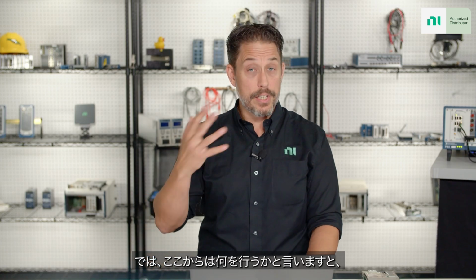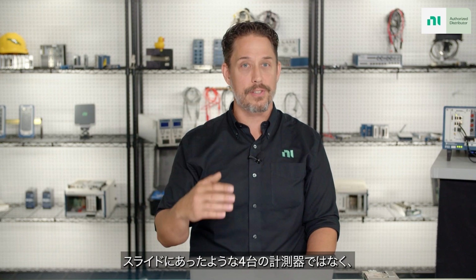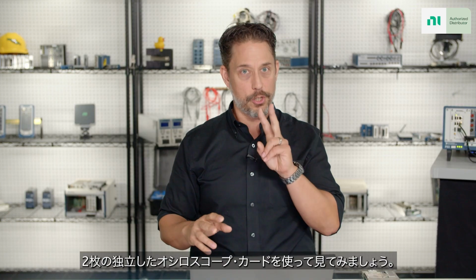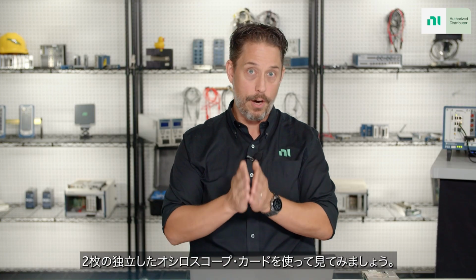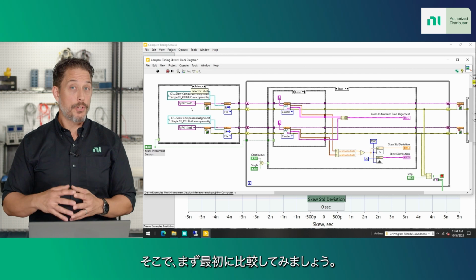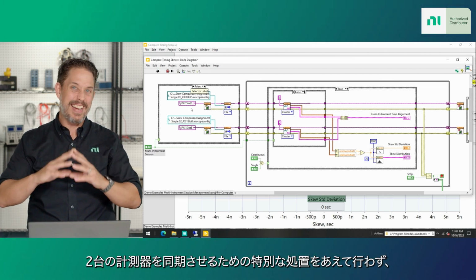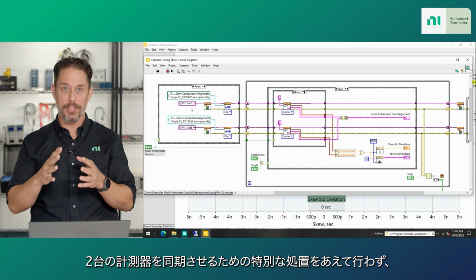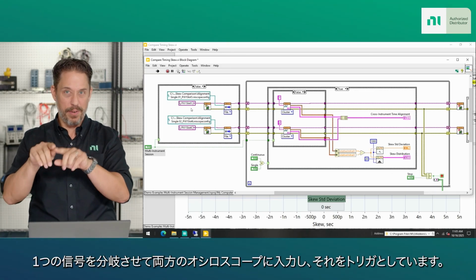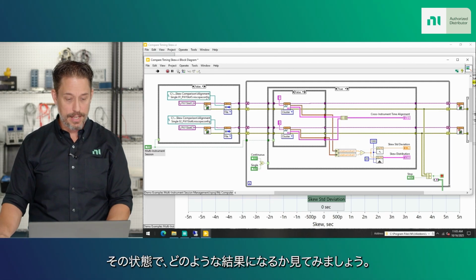Now, what we're going to do here is look at this actually running live and see what this looks like for not the 4 instruments that we have in these slides, but rather just the 2 separate oscilloscope cards, once again, looking at those 2 separate aligned channels. So what we're going to start off with here is comparing what it looks like when you don't take any effort to get those 2 instruments aligned, except using the exact same signal that's incoming. We kind of branched out one signal to both scopes to trigger off of. And let's see what that looks like.